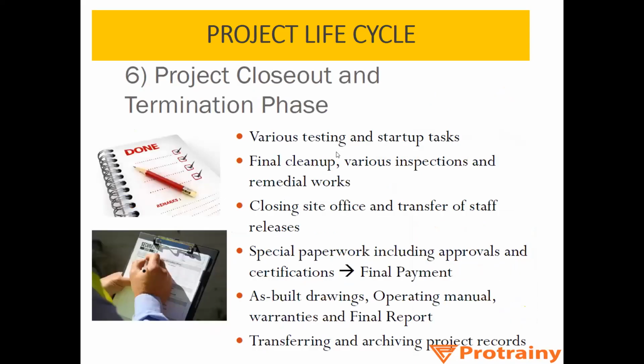Then the final sixth phase, which is project closeout, when the construction is completed, and then you are testing and repairing if repair is required. So various testing and startup tasks need to be performed. Final cleanup, various inspections and remedial works. You need to close the site office and remove it from there. Transfer of staff you need to do, to your other running projects. Then special paperwork, including approvals and certifications. Final payment you need to get from the client. As-built drawings, operating manual, warranties, final report, and transferring and archiving project records.